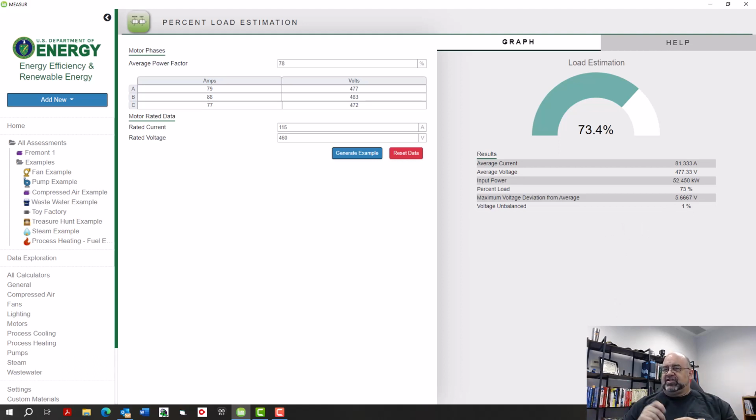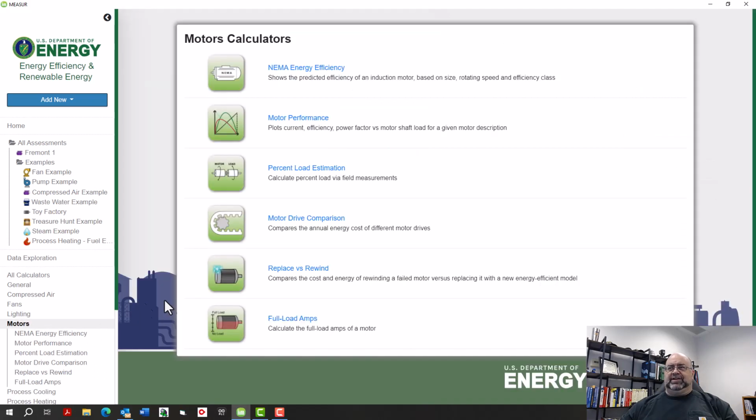I've had these discussions before, and it really depends on the goal of the person you're talking to. Oh yeah, improve the shaft horsepower. Okay, but what is my actual energy cost? Oh, but the shaft horsepower is good. What's the energy cost? So if you reduce the shaft horsepower, but you've done damage to the machine so that the input power goes up, you really haven't fixed anything. So when I use examples like that, it's something I've run into recently.